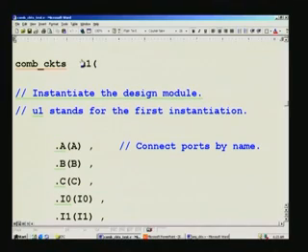This is U1, you may have another U10, you want to connect a particular pin to U10 from some other pin. So, you have to declare that as a net or a wire. That is the funda in declaring all the outputs here as a wire. Are you clear? The output is defined as wire. The next chip's input will be regular, right?